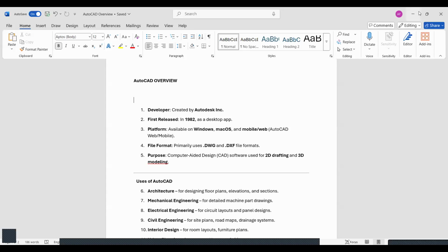Multiple means you want to select multiple things, and there is polyline, there is circle. If I want circles by layer, by color, by line type, by line scale, line width, or any other property. Right now I'm doing it with colors. The color is by layer, then I'm clicking OK. Now you can see each and every circle got selected.